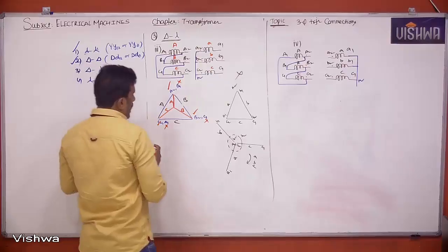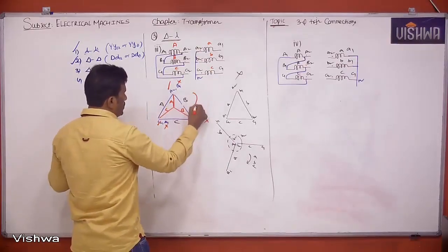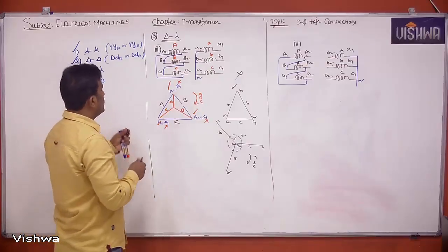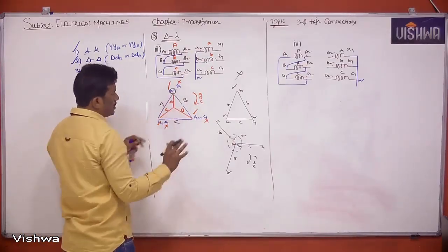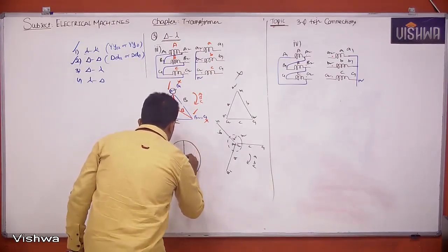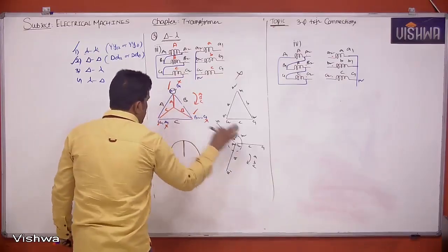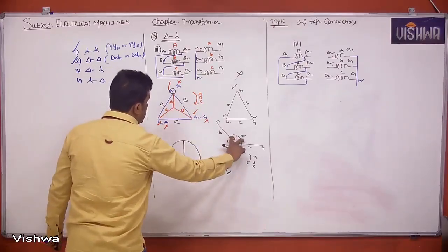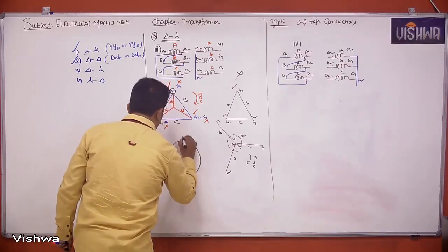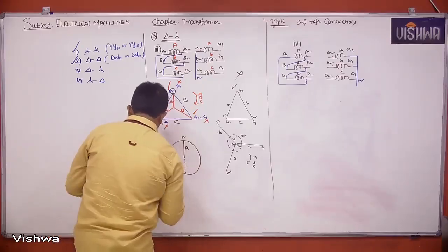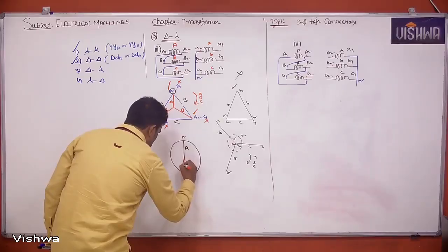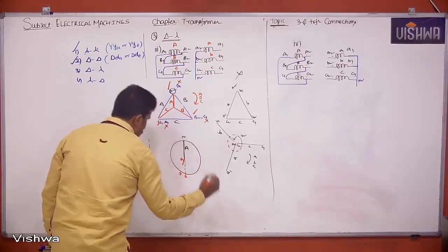Okay. And what you have to do? What is the phase sequence here? ABC is the phase sequence here. Whenever the phase sequence is the same, then only you can start comparing. Now since I have taken A2 as reference, just compare small a with the capital A. That's it. In a clock, this star is just taken and kept on this star. This capital A represents the minute needle, the long needle. Small a represents the hour needle. It is at 7 o'clock.